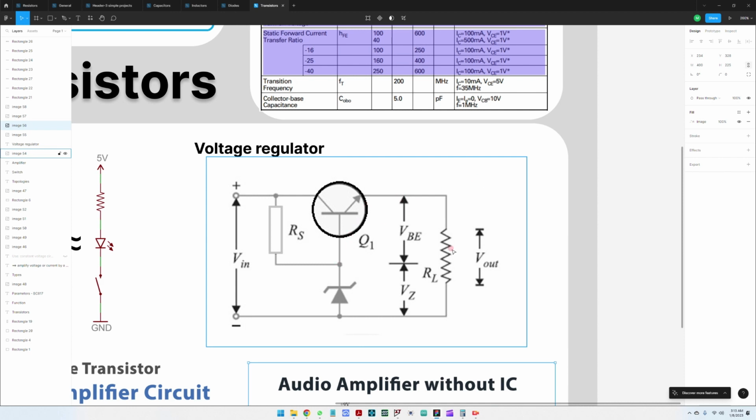We will discuss this a bit more in detail in the simulation part, where we can create a couple of voltage regulators, and it would be quite an interesting challenge to create different voltage levels. It's just repeating the circuit and understanding that if you need a 1.8 voltage level for the circuit, you can create one with a transistor, a resistor, and a Zener diode.